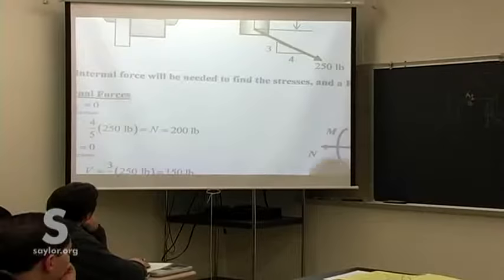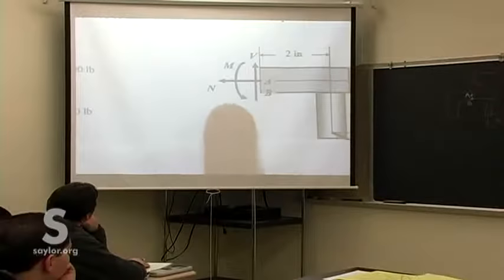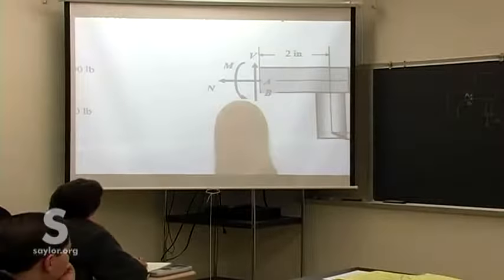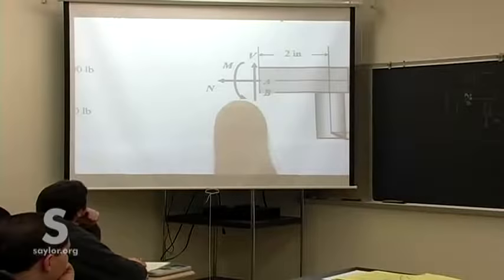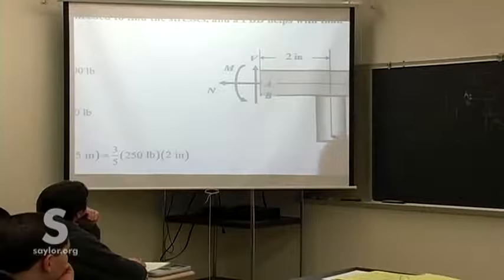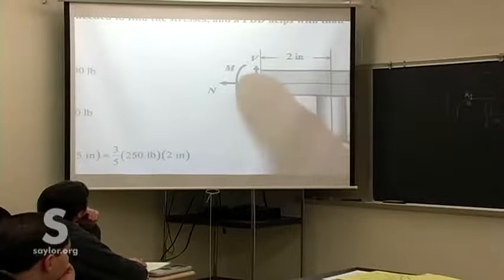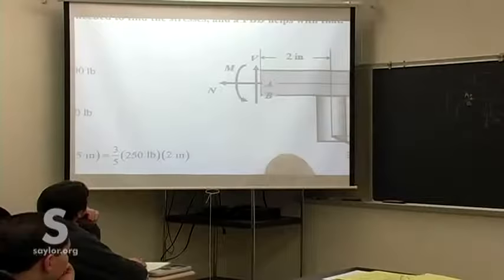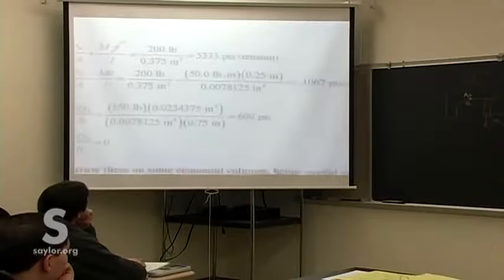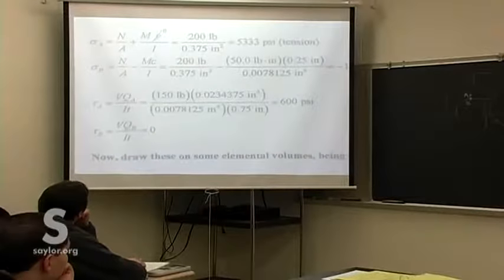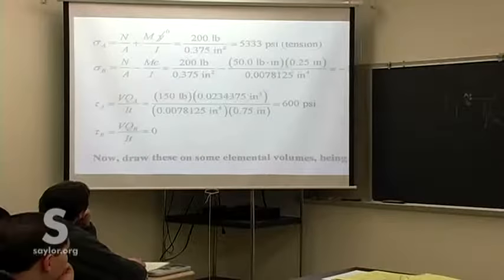That came out because I found that the bending is in this direction at that interface, doing a free body diagram of the piece itself. There's a horizontal component causing bending in one direction, a vertical component causing bending in the other direction, and it was the horizontal component bending it this way that was the dominant. And so the total effect of M is compression at the bottom, and thus the minus sign between the two.